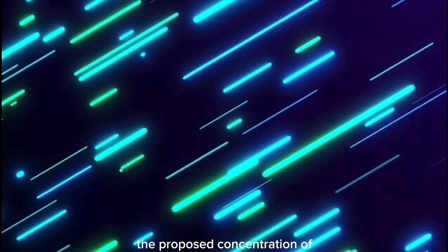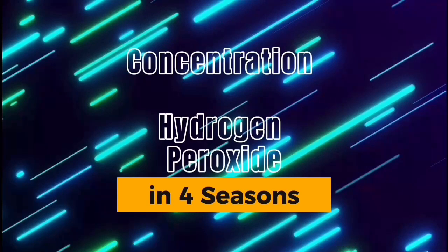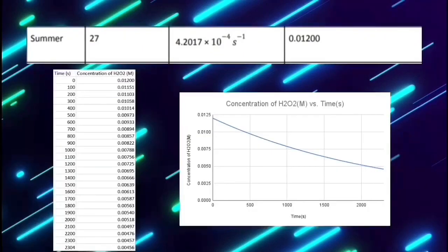The proposed concentration of hydrogen peroxide against time is as follows. The rate constant for the first season, summer, is 4.2017 × 10^-4 per second. Therefore, the initial hydrogen peroxide concentration requirement for the summer is 0.012 molar.